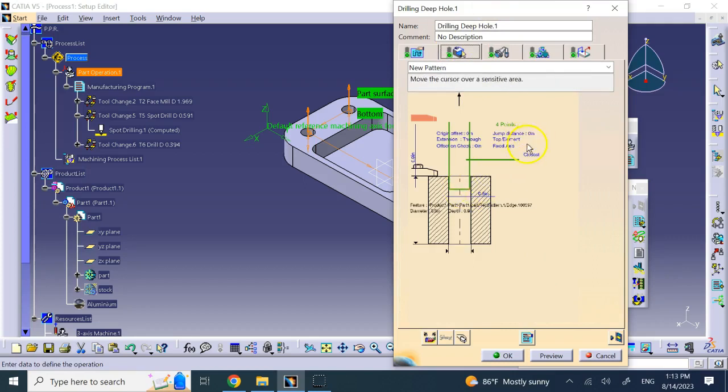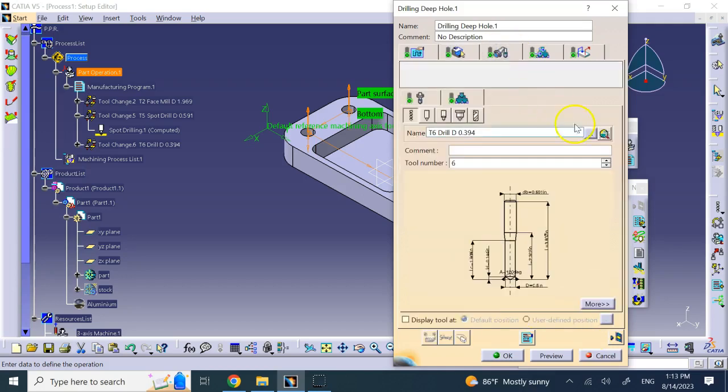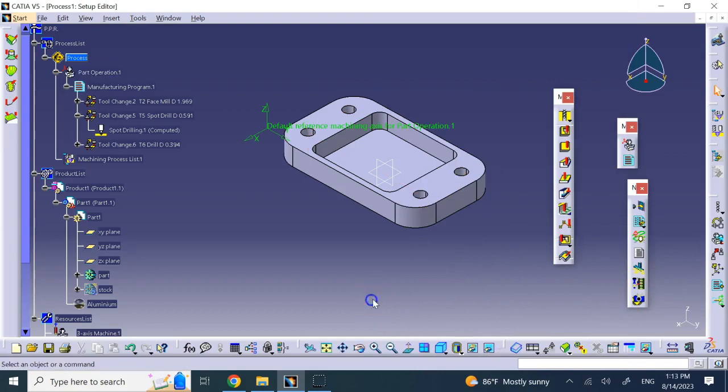But if you can see here, there is no offset for the bottom plane. Okay, there is offset on the check, but there is no offset all the way down and below the bottom surface. So that is not going to do the perfect cutting, and that's why I basically created this angle to be 0 or 180, and that will do that cutting all the way down.